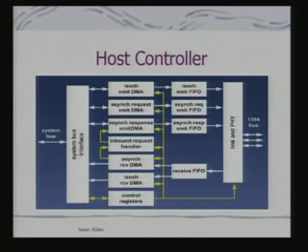So, this interface is typically part of a PC, when the PC is one of the IEEE 1394 devices. It would be part of any other embedded system when that itself is participating in the IEEE 1394. So, you would expect a similar kind of controller even with your video camera, which is IEEE 1394 enabled. But a video camera may not have an extended interface for receiving data, because it is supposed to transmit the data in response to a request.